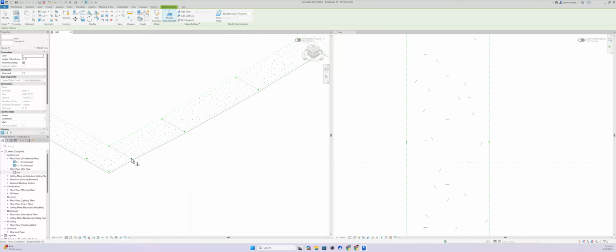Okay, so now I have a little ramp going down, a flat surface, and now this one is going to go up. So it can be 2 inches or 4 inches. I can put minus 4 inches on each point. This is what the civil engineer does when it comes to grading. So here I'm going to put minus 0 space 4.